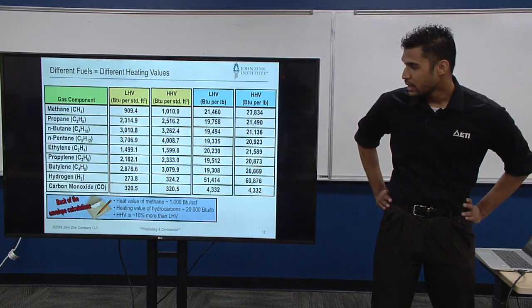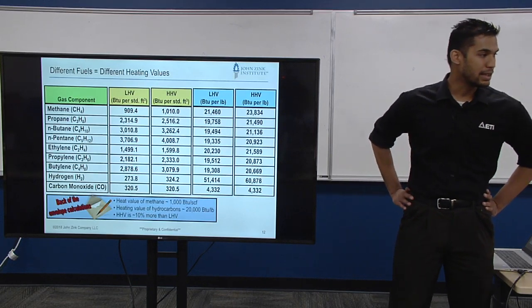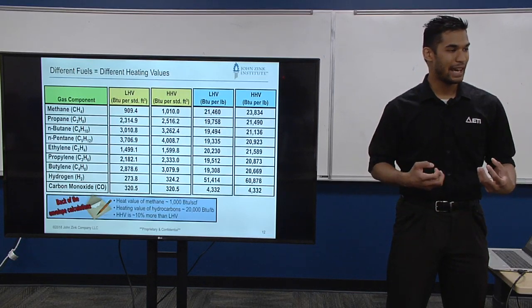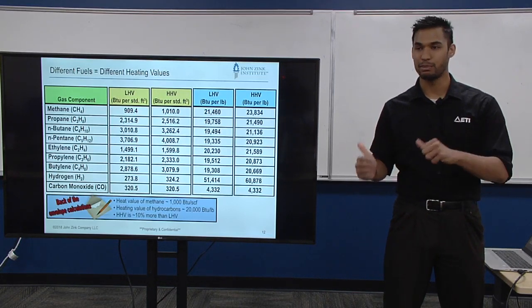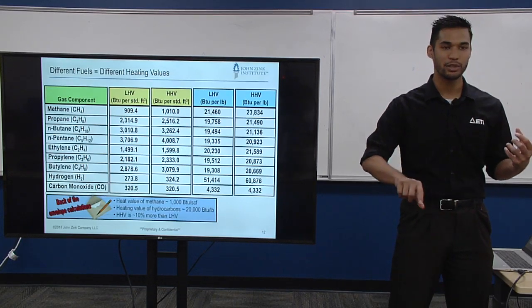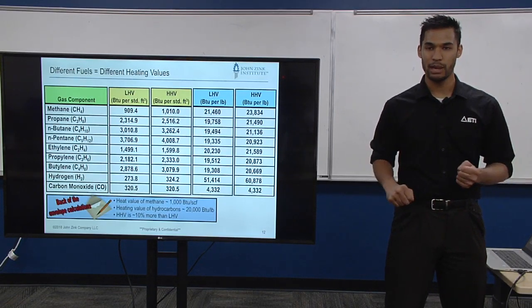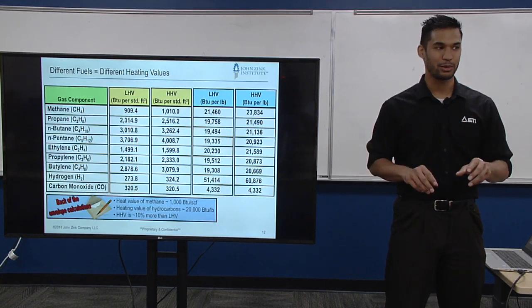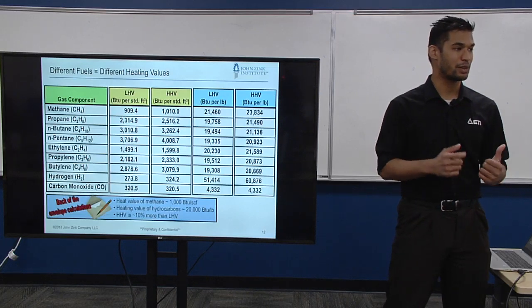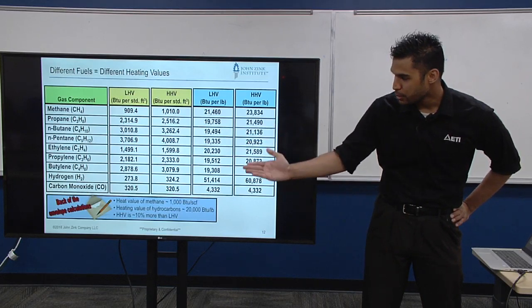Let's see, propane. You can see the BTU per scf value is much higher, right? So per standard cubic foot of propane, you're going to get a lot more heat than if I'm firing and burning methane. So can I just willy-nilly switch out? I'm flowing a certain amount of methane to my burners, I'm running my process, and they say, we're out of natural gas, can we just switch over to backup propane? Do I need to flow at the exact same rate? I'm going to be throwing in a lot of extra heat, and a lot of bad things could happen if you don't understand that there are differences between fuels. Okay? Ethylene, propylene, butylene.